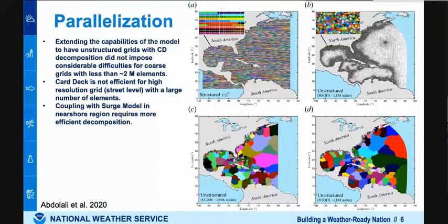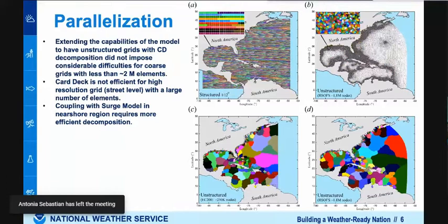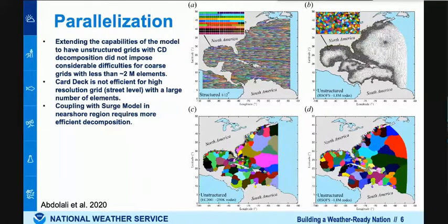In the upper right-hand side, we use the same algorithm on an unstructured grid. It's a 1.8 million node grid, HSOFS, and as you can see, the grid nodes are distributed based on their index on the computational cores, so it looks like some kind of random shape. And in the lower panels, we have used the domain decomposition, the new algorithm that we have implemented, using Metis and parametric libraries on two unstructured grids.